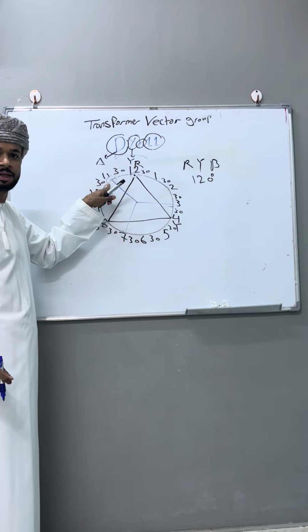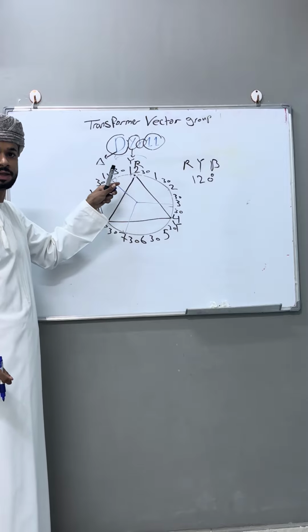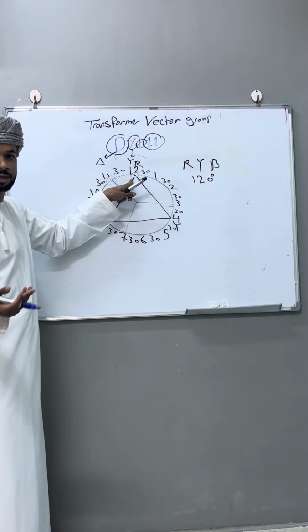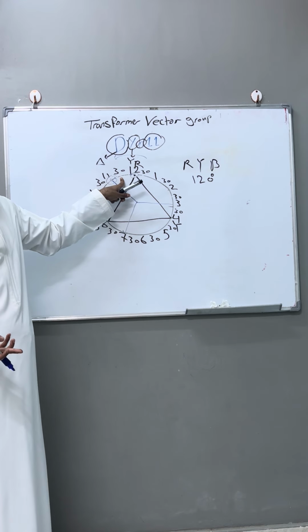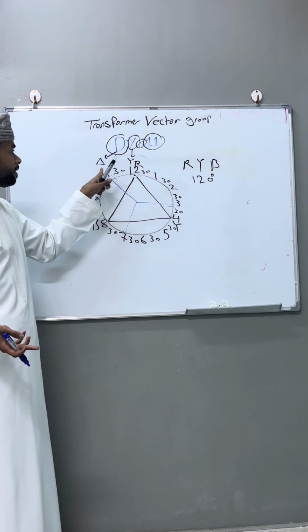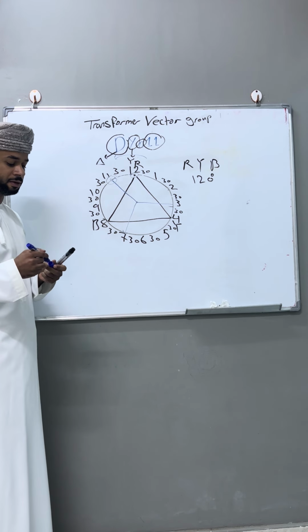The secondary side leads the primary side with a phase shift of 30 degrees, or we can say the primary side lags the secondary side by a phase shift of 30 degrees. Okay, and this is what Dyn11 means in the vector group.